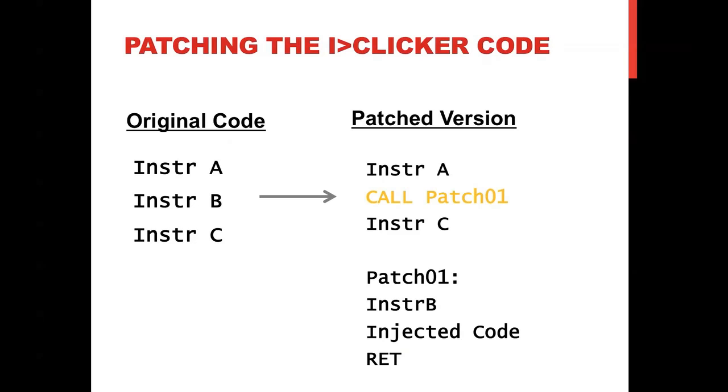By jumping to an empty segment in program memory, we could inject any kind of code we wanted, as shown here. Now, a point worth noting is that the disassembler we used that came with AVR Studio used PC relative addressing. This meant that anytime we replaced a line of code with a call to another segment, we had to ensure that the size of the instruction used matched the one that we were replacing, as to not mess up the code space and shift down the whole addressing. This was sort of annoying, but we were able to get around it.